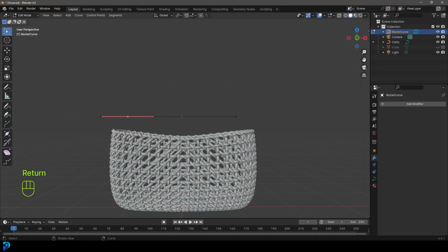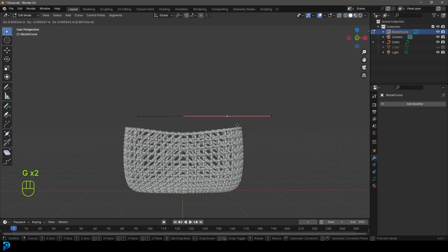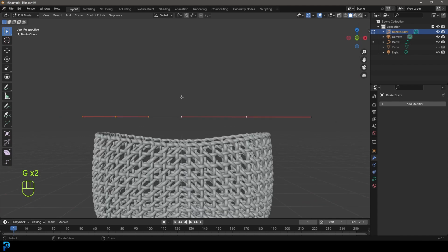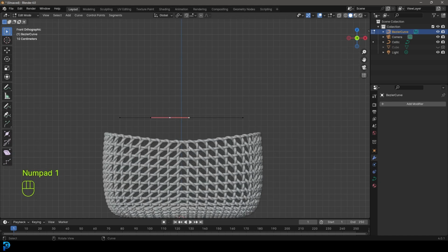And what we've got here are two handles. We've got this handle here and this handle here. So we're going to select both of them, and we're going to right click and go subdivide. And now we've got this middle handle. So we're going to go in our front view and just lift that middle handle up, S to scale, and then let's grab this handle, R to rotate, and then G just to move it down, and do the same with this one here. Select it, rotate it, and then G to move it down.